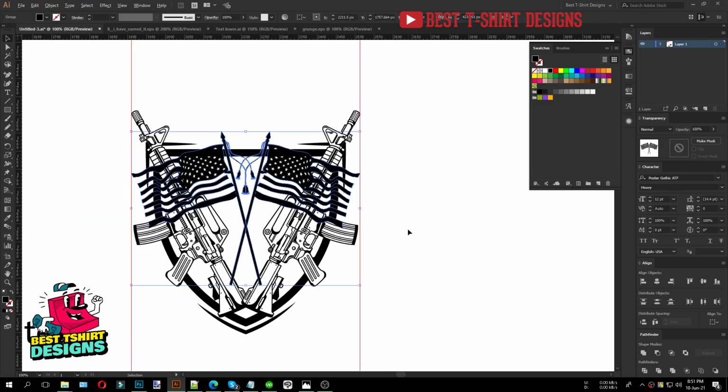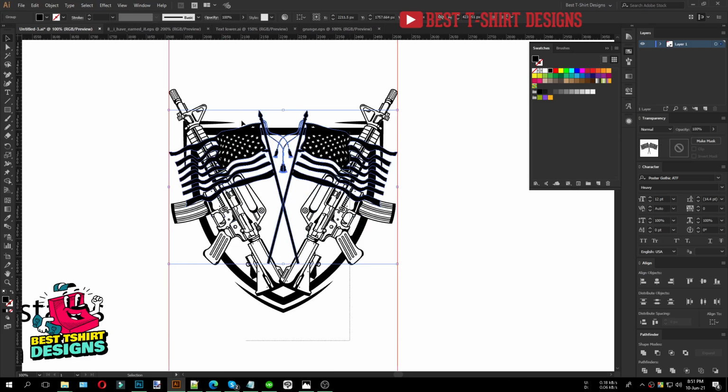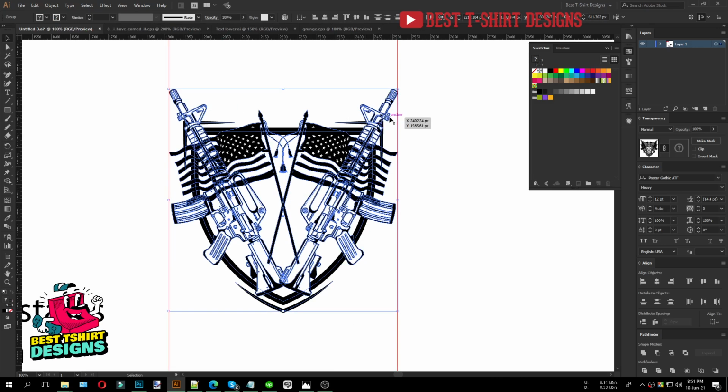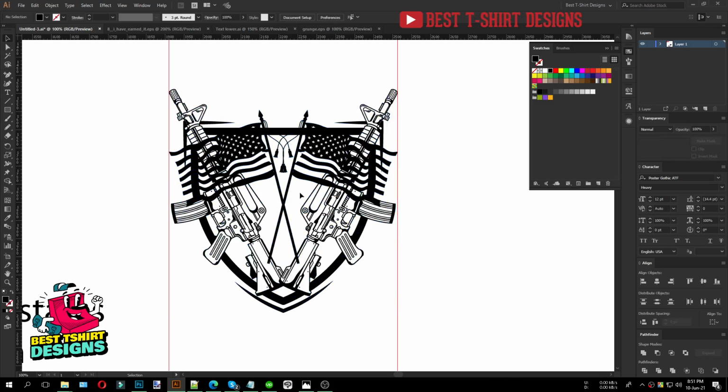Let's make them a group, and if I select them all like this, I can simply click on any of the objects, that will become the key object. Now if I align them center wise, everything else will be aligned with the key object's position. So that much is fine for me.